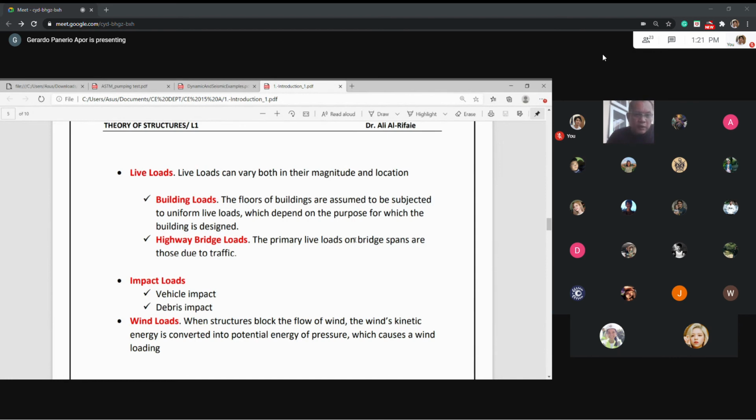We are going to study these loads now. If the structure is residential, you apply its self-weight, the dead load, and the occupancy load. Sometimes we apply earthquake load because we do not know whether an earthquake will occur during the lifetime of the structure. If you do not include earthquake and one happens, an additional force is added to your structure that it was not designed for, so it becomes overstressed or sometimes damaged.